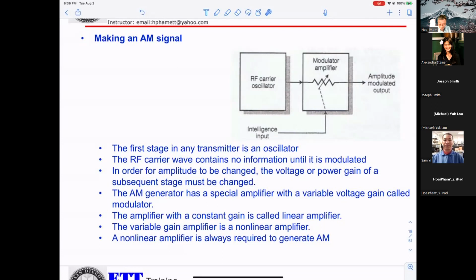That amplifier has a gain, and the gain cannot be changed. It has a fixed value. Gain equals 10. That means gain equals 10. No way you can change the gain to a different number. You can change it, but you have to change the value of a resistor, like the gain of the inverting amplifier, RF over R1. If you want to change the gain, you have to change the value of RF over R1. That's what they call linear.